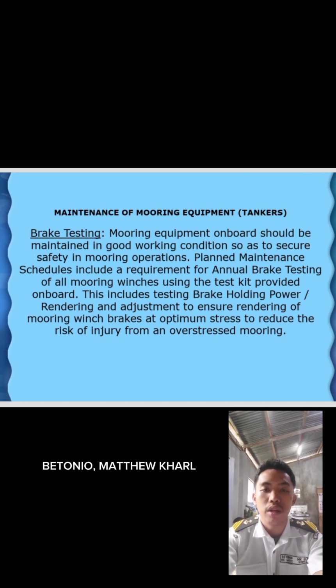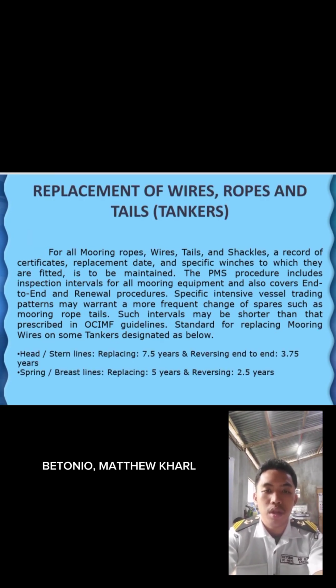Replacement of wires, ropes, and tails. For all mooring ropes, wires, tails, and shackles, a record of the certificate, replacement date, and specific winches to which they are fitted is to be maintained. The PMS procedure includes inspection intervals for all mooring equipment and also covers end-to-end and renewal procedures. Specific intensive vessel trading patterns may warrant a more frequent change of spares such as mooring ropes and tails. Such intervals may be shorter than that prescribed in